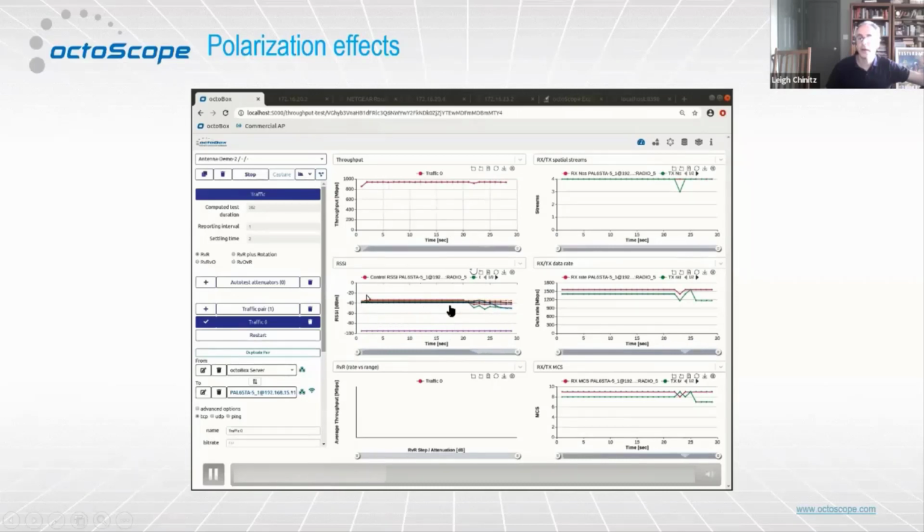And what I'm doing in this test is, one by one, rotating the antennas as just shown to go from linearly polarized to cross-polarized, and you can watch as I turn down each one of those antennas, the received signal level drops. And let's take a look at the details behind that drop.